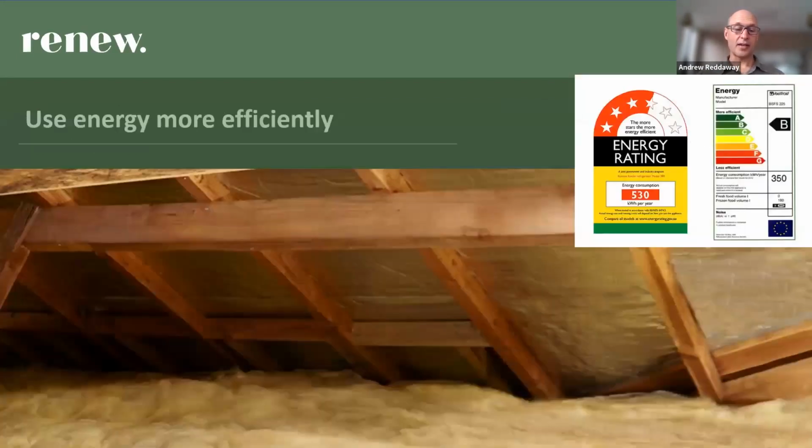And another basic is energy efficiency. Today we're mostly talking about generating electricity with solar panels and storing it in batteries. But the best form of energy is the energy that you didn't need to use in the first place. The example here is insulation in the ceiling cavity. That's insulation batts over the plasterboard in your ceiling, like a blanket to hold the heat in winter and to resist the heat soaking through in summer.